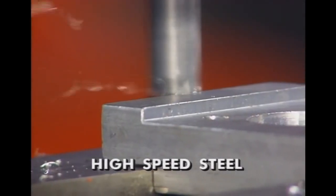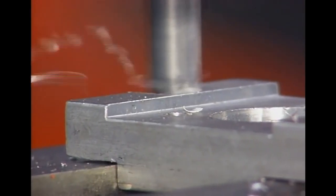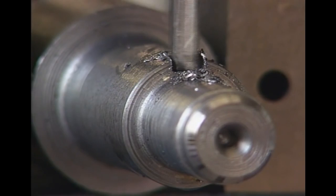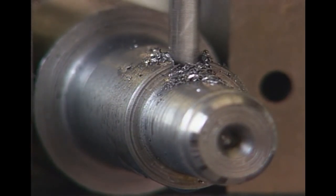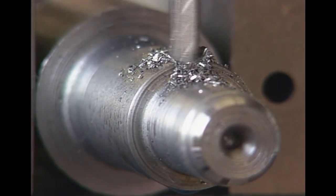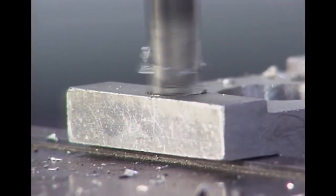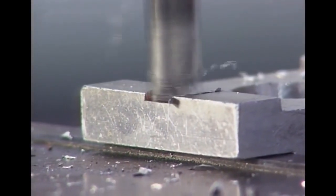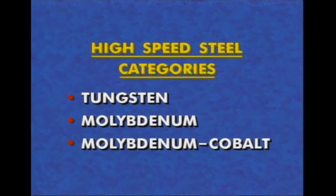High-speed steel tools were introduced around 1900 and gradually replaced the carbon steel tools of the 19th century. High-speed steel cuts about 4 times faster than the carbon steel tools they replaced, hence the name high-speed steel. It operates at temperatures up to 600 degrees centigrade. There are over 30 grades of high-speed steel in 3 main categories: tungsten-based, molybdenum-based, and molybdenum cobalt-based.